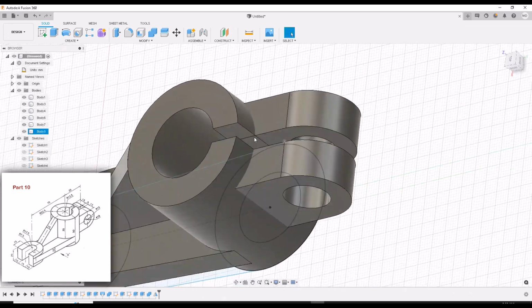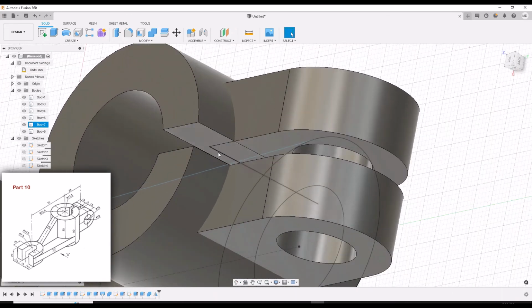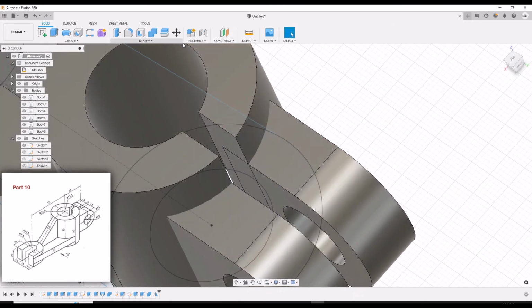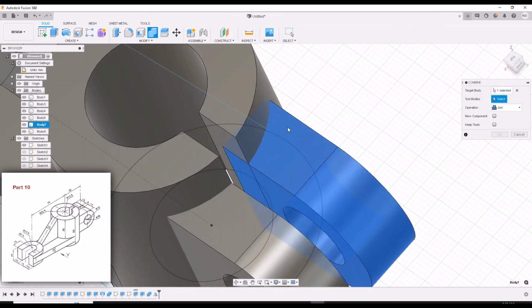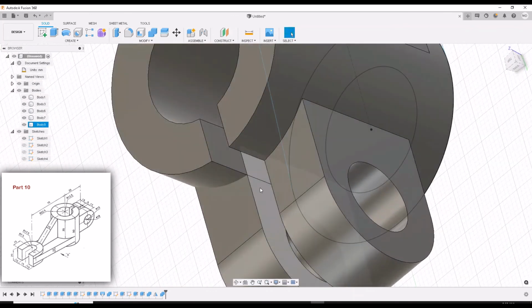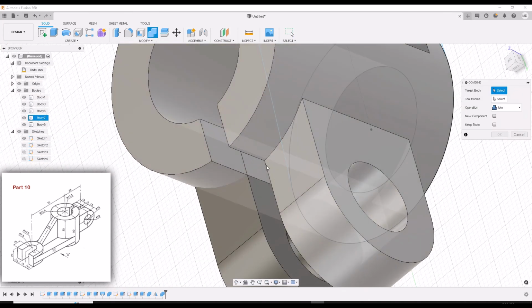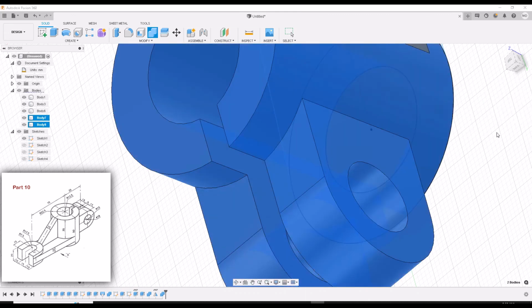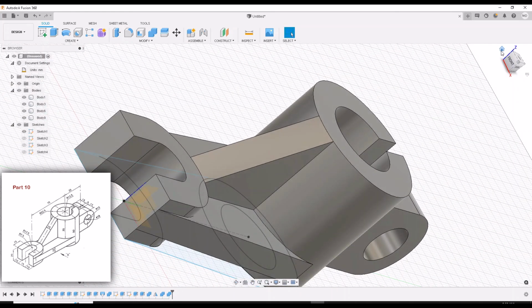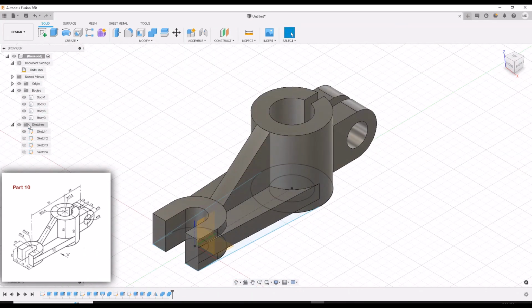Now, you notice we got extra line segments in here. That's what happened when we join the parts and stuff. So let's combine. Let's make it nice and neat now. Join. See how I did that? It got rid of those line segments. Let's combine again. Join, and there it is. It cleaned it right on up. So if you go to your isometric view, you just turn off the sketches. You just want to make them invisible. You turn off the origin too. All right, there it is.